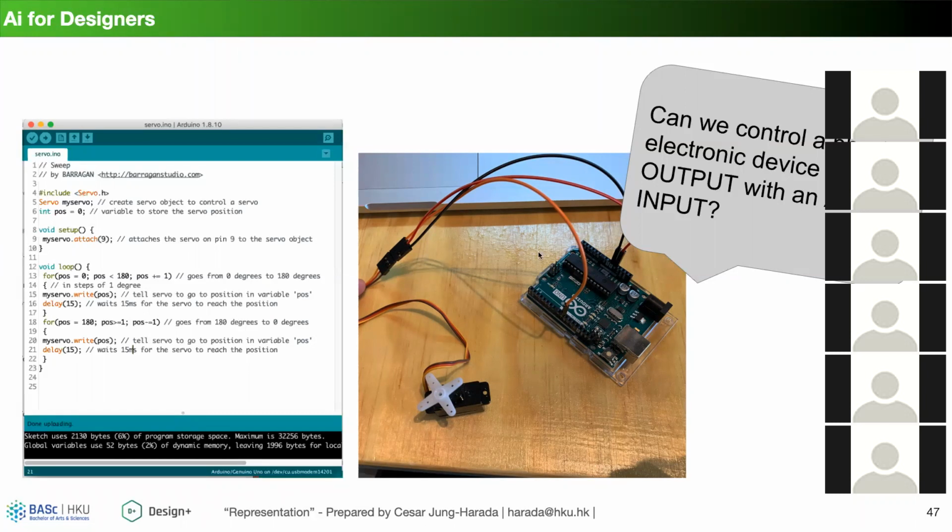Okay. So what I'm going to do, instead of loading this Arduino code, is load a small Python script, which is going to try to see not if I'm smiling, but where my face is on the screen. The screen has a value of 0 on the right and 1024 on the left. If I'm around 500, in the middle, it's going to know, okay, you're in the middle, good, I don't need to move. But if I start to move away, say 100 points, so if I go less than 300 or more than 600, then it's going to try to go left or right.